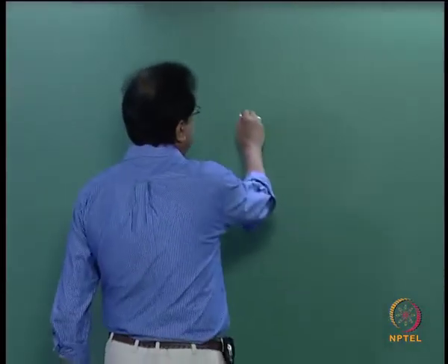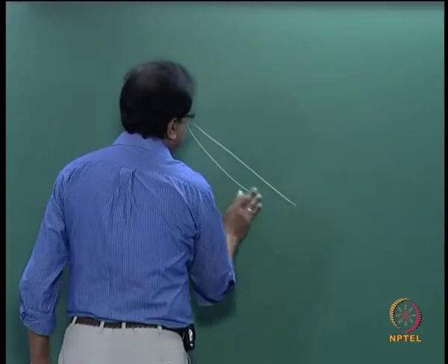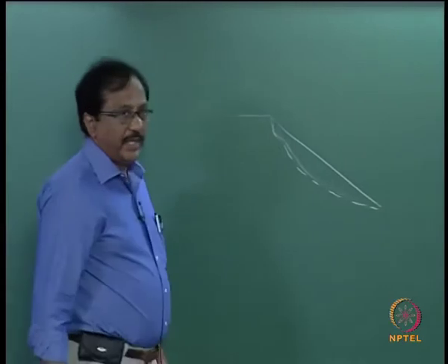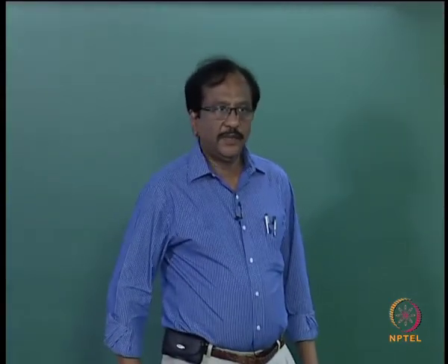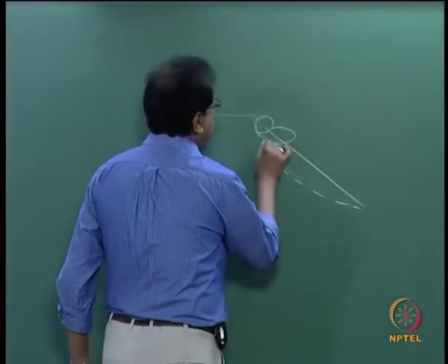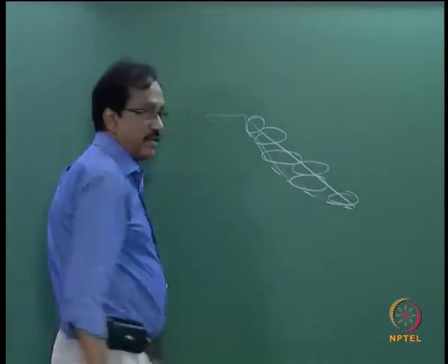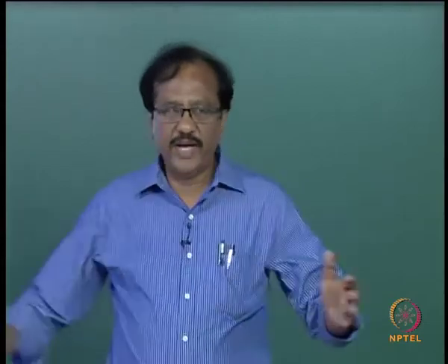So usually what will happen if you have a bank getting eroded, if it is getting eroded like this, how do you protect? As an immediate measure, what they do is they dump gunny bags, in the sense sandbags, bags filled with sand.